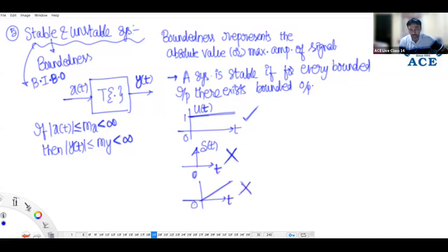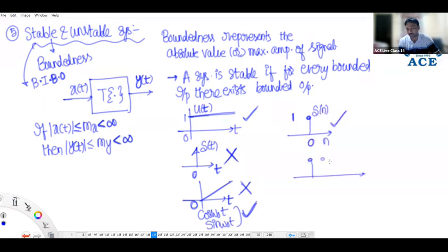No. What about cos and sine functions? Of course, they are bounded. Amplitude variation of plus or minus 1, answer is 1. So in the continuous case, the bounded inputs are u(t), cos and sine. Discrete case, both the standard signals are maintaining finite amplitude. Delta has amplitude 1, u[n] amplitude also 1. Both are maintaining finite amplitude. Don't apply ramp signal as input and say system is unstable, sir.